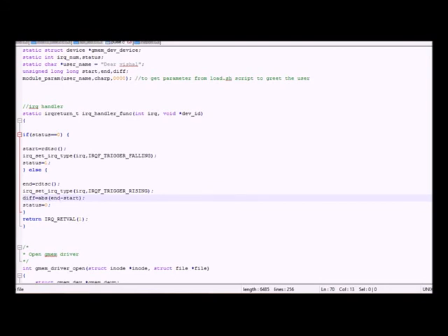and then we try to make our animation. Here in our dog animation, I've taken the distance to vary the time or the delay between two patterns. So when the distance is near, your dog seems running, and when the distance is far, your dog seems walking. So this is a very simple kind of animation, and using this assignment we have got to know about SPI, LED matrix display, interfacing the ultrasound sensor, and we got to know more about the interrupt handlers and kernel thread.